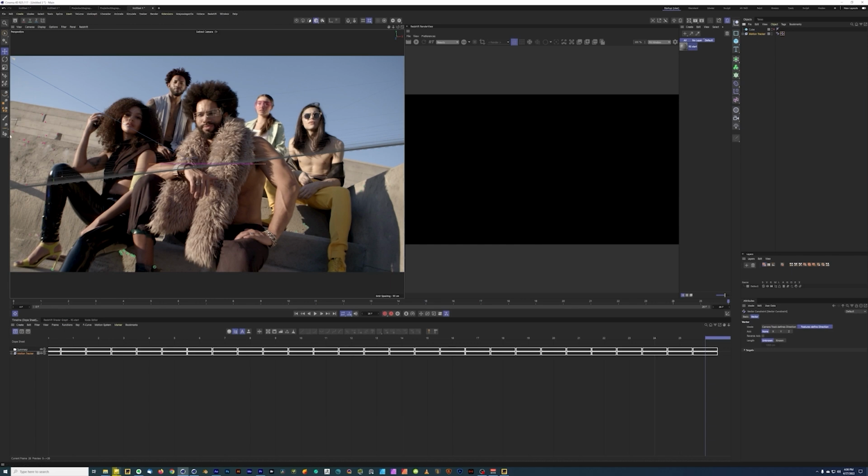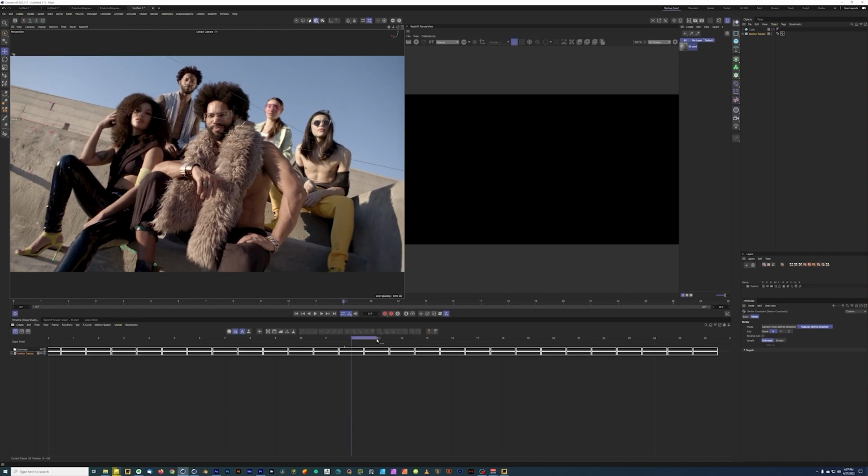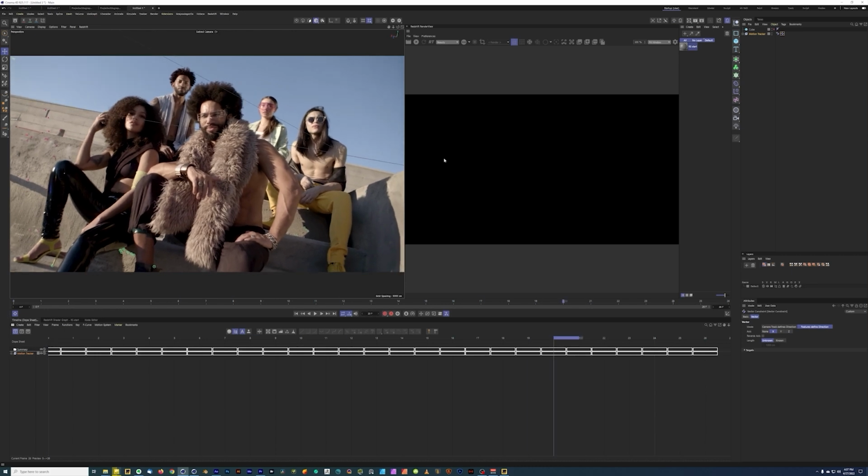And so right now I just want to tell the computer that this is the x-axis. So it's given me this line here. So I'm going to put this one on here, and I'm going to put this one right here, and I'm going to say that this is the x-axis. Just when I click that X, look what happens now. Now our horizon is pretty lined up.